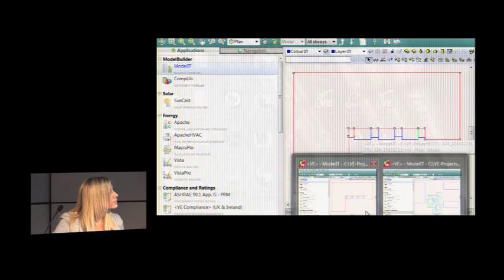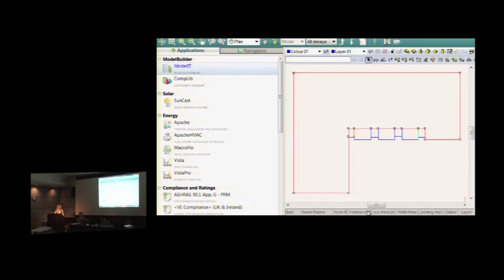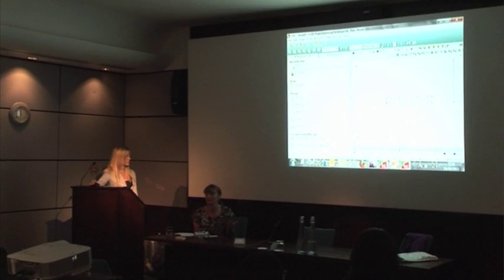I'll just say the reason for that is that when the VE is running its calculation, it's obviously calculating the effect of every single one of those surfaces. So basically that's why, if you're doing a sun cast calculation, it's calculating how much sun is hitting those individual elements and how much is being reflected, or how much solar radiation they actually absorb.